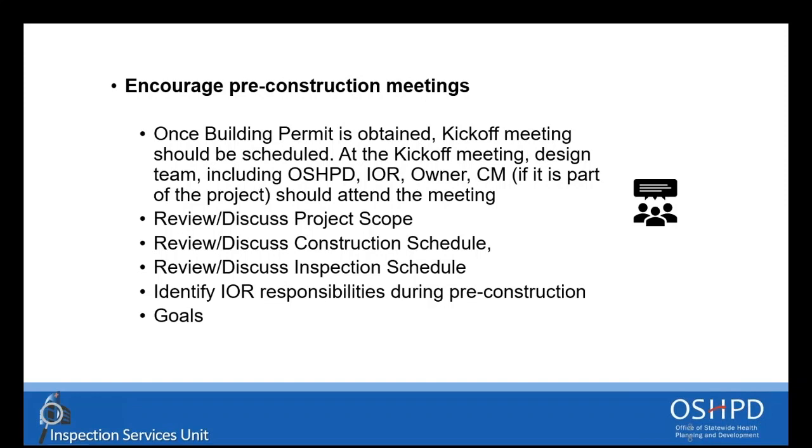Before all the construction begins, there should be the pre-construction meeting, the kickoff meeting. This is a very important meeting. What should be discussed during this meeting? Who should be part of this meeting? The DPOR, including also the OSHPD staff, the IOR, the owner, the construction manager, if he's part of the project, all of them should attend the meeting. Scope of the project, construction schedule, inspection schedule, IOR responsibility, goals, all of this should be discussed during the kickoff meeting. I will overstate it: do not underestimate the kickoff meeting. The better you set up everything, the better the project could be, because there will be no misunderstanding.